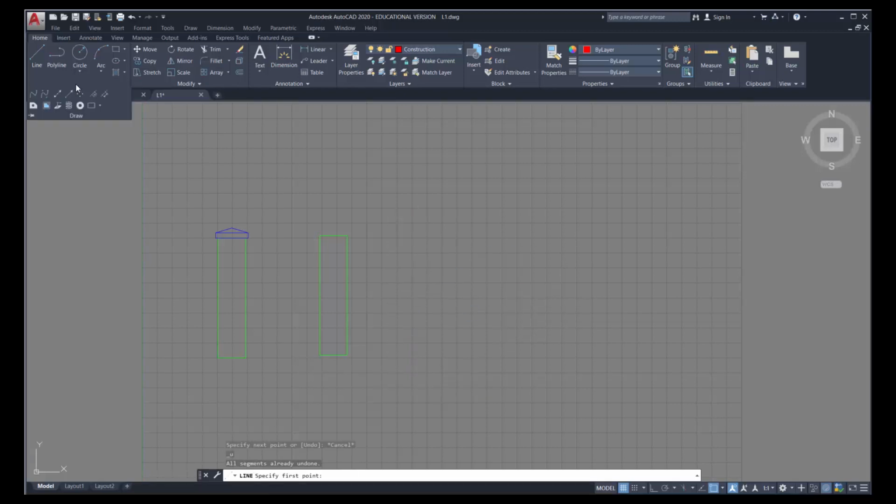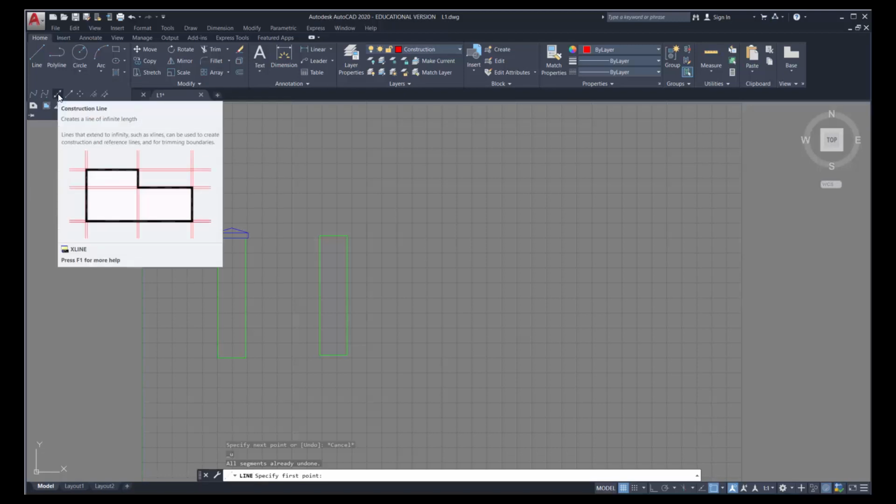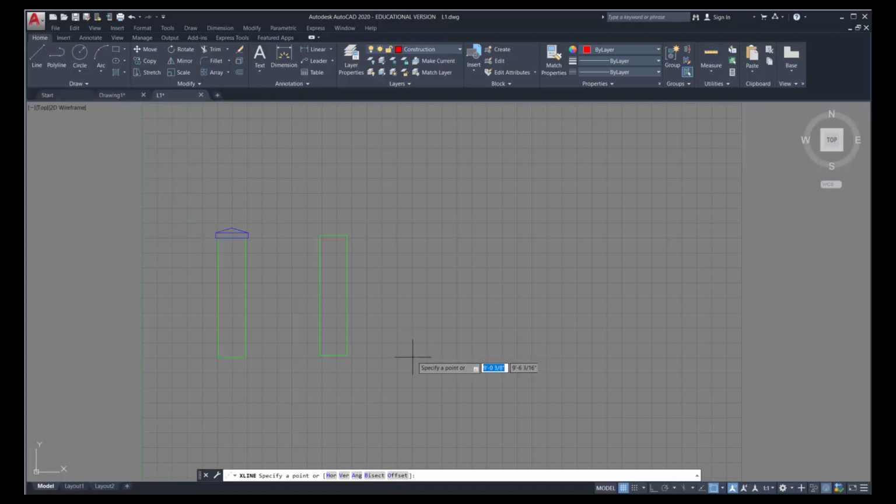So in the Draw menu, there's this icon here. It has a single node in the middle and then arrows that go in opposite directions. And what I'm going to draw is from the base of this column, a line up and a line sideways. Now, in order to get that perfect horizontal and vertical line work, press the F8 key at the top of your keyboard.